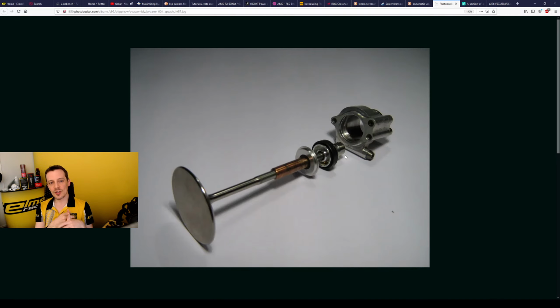And this is actually really efficient from all kinds of standpoints. You can vary the pressure rate and have pressure relief stuff and things like that. So you can have a little bit of non-linear valve action also, so that when you're compressing the valve, you can let out a little bit of gas depending on what pressure you want to be running at. At higher RPM you can run higher pressures, and at lower RPM when you don't need a really high pressure, you can just lower the pressure ratio you have there.